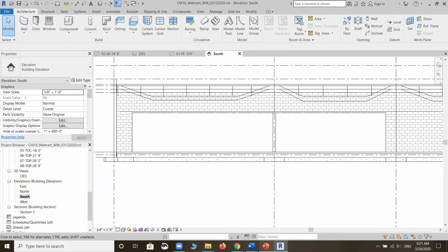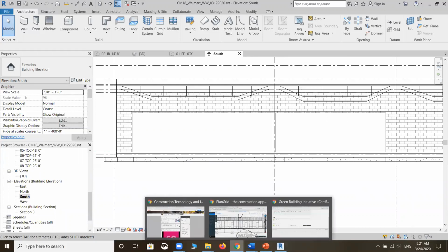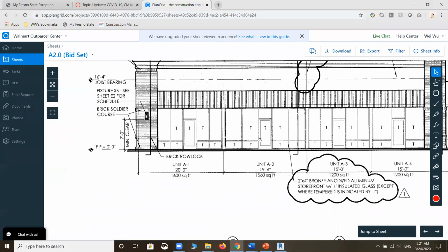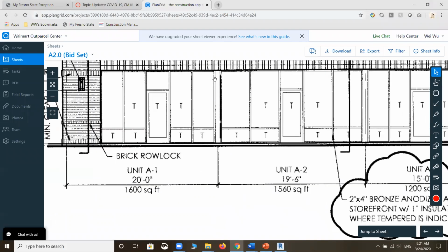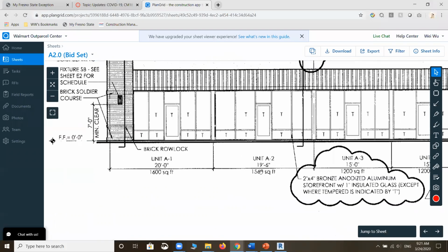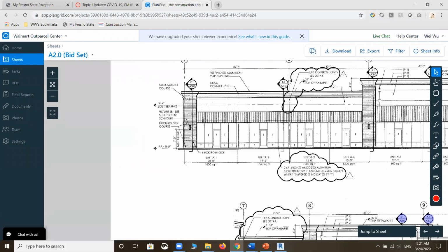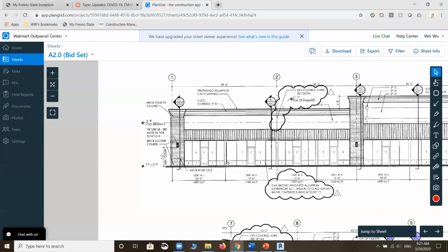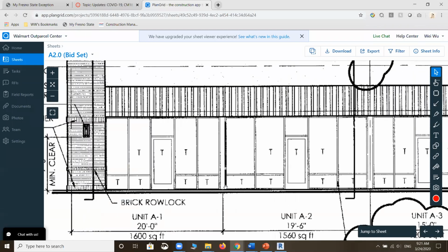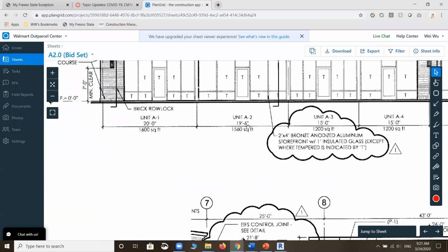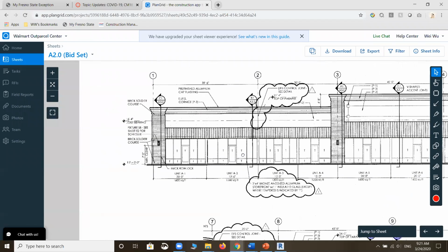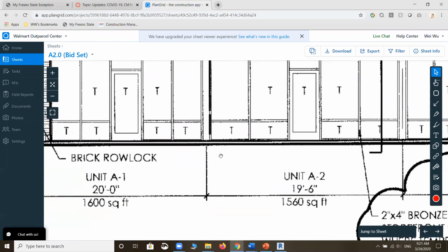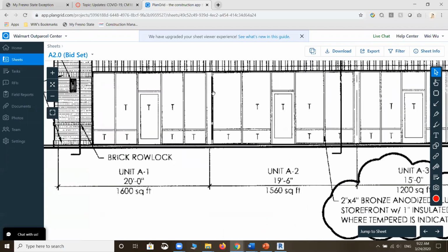Then the next one here. How far away is that panel from grid line number 2? This little small panel right here is 19 feet 6 inches away from grid line number 2. I don't really have a cutting grid here, however, we can pretend that we have one here.